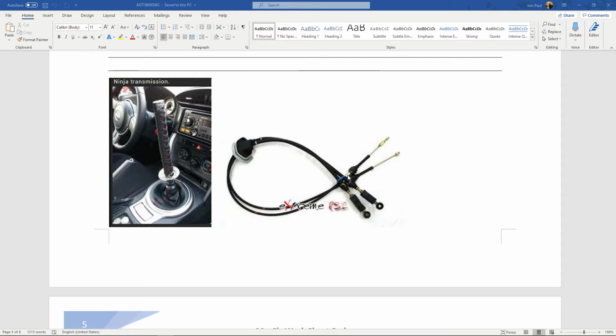So I put a clutch in a Sentra, and the mounting bracket for this selector cable got bent. So you get in the vehicle to drive it and go left to find first and second, but the literal selector here, this lever, would travel too far to the left because the cable wasn't where it was supposed to be. So that's going to be rare, very uncommon. By itself, it's never going to happen. It's not going to bend itself.